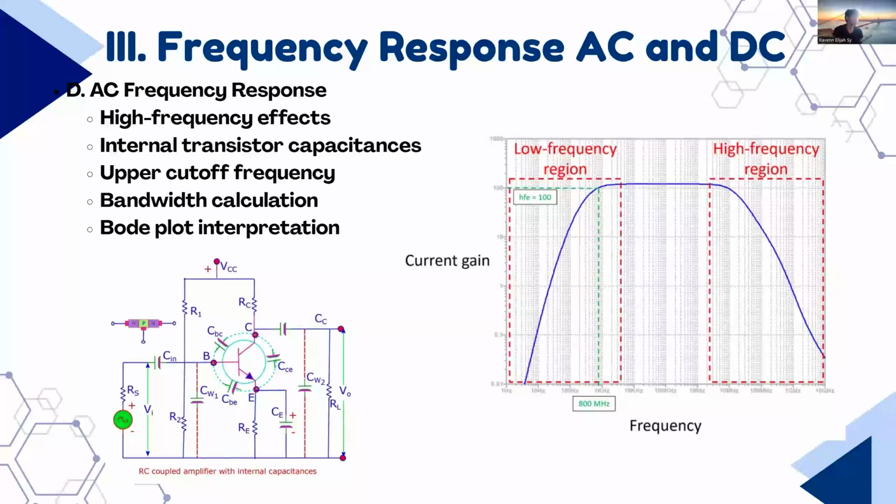Any capacitance connected between input and output terminals, like the base to collector capacitance, is mathematically multiplied by the voltage gain of the amplifier. This creates a much larger effective input Miller capacitance, which severely restricts high frequency performance.